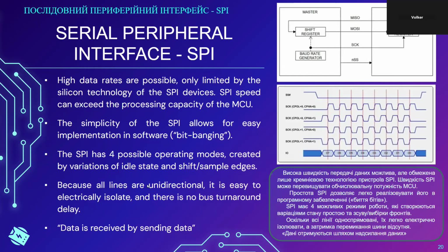This is called colloquially bit banging. It works very well for the SPI interface because there is no effective protocol. It is just pushing data into shift registers. The code amount to do this is small. The processor doesn't have to wait.